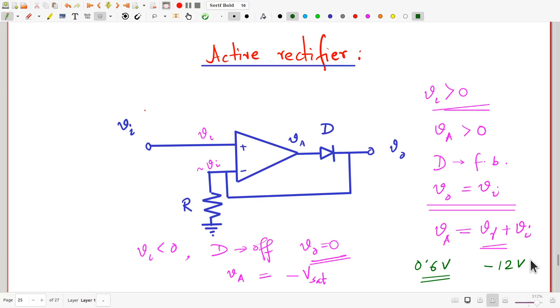The slew rate actually is an important issue which can come up in other kinds of applications as well. For example, maybe you're just using an inverting amplifier and you feed in a sinusoidal input and you expect that the output would be a nice sinusoid. That will be fine unless you go to high enough frequencies and or large enough amplitudes. Then what would happen is that the rate of change of the output voltage that a sinusoid would impose may be way too large for the particular op-amp that you're using. And then you're going to end up with a waveform which does not look sinusoidal at all. The waveform will end up looking triangular.